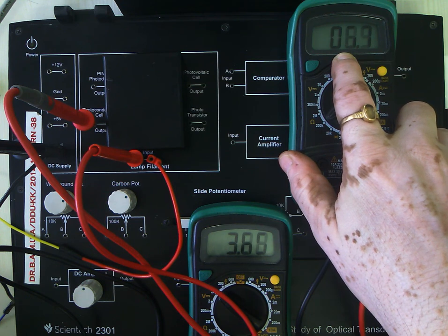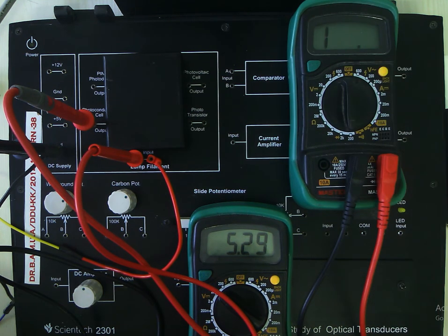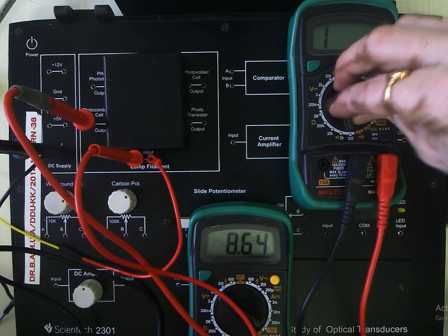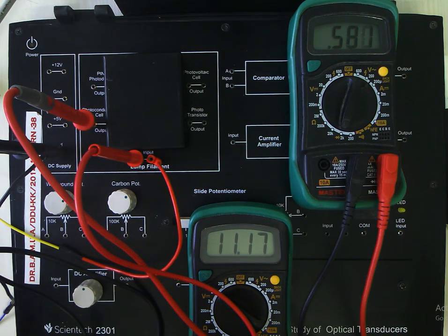As I will keep on increasing the filament voltage, you can find the resistance value is very less. Okay, you see? Yeah. So in 2K range, it's 0.737, that means 737 ohm is the resistance. So as you can see, but definitely the resistance will not be completely zero at any point of time.